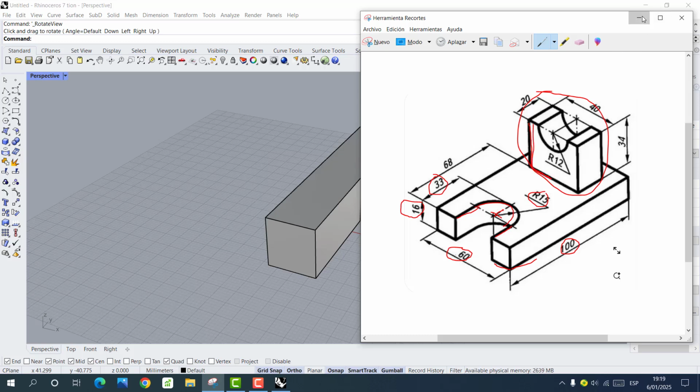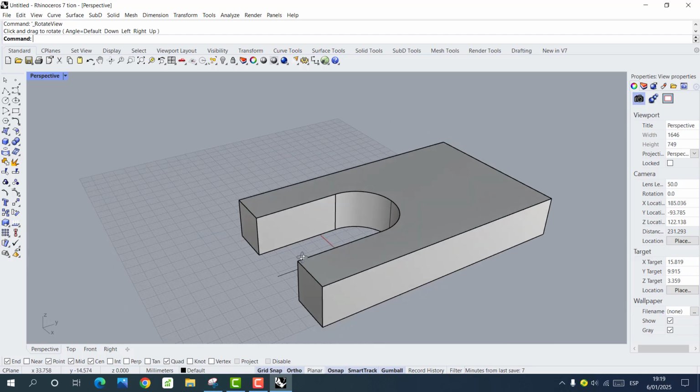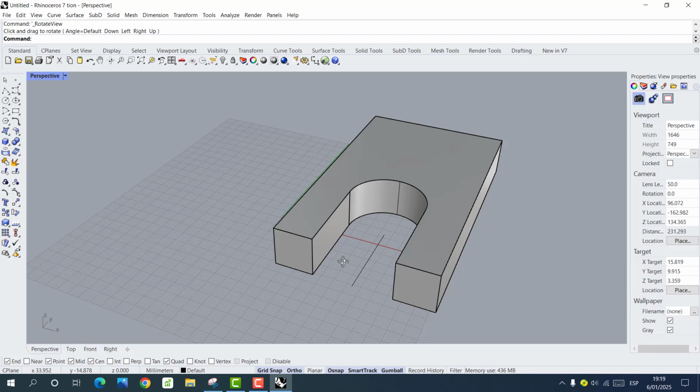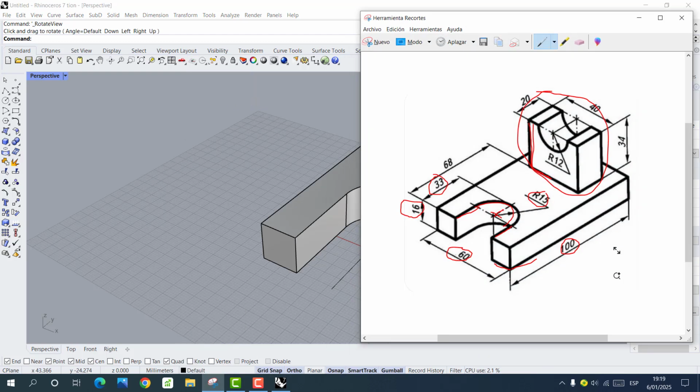Now we can change the plane. This object we can obtain by the C-plane command, or this button set C-plane by 3 points. Now we can center for this body,